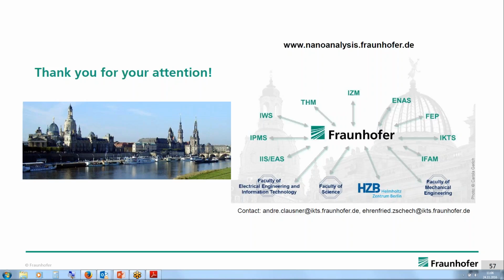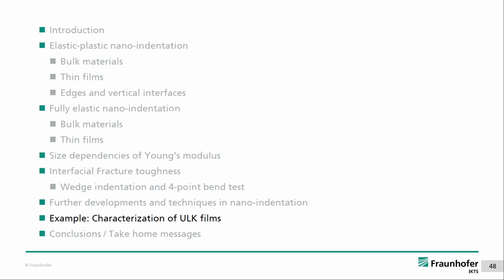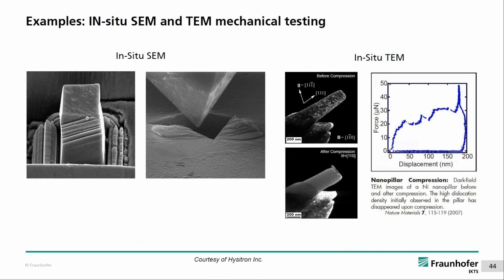The first stage is elastic deformation. If it's a hard material, you can determine the elastic parameters of the nanoparticles from analytical solutions, and if you compress it more and you are in situ, you can see what happens. Either there is plasticity, you see slip lines and so on, as I can show here. This is a pillar, but you can also imagine this is a nanoparticle, and you can see here the slip lines of the plasticity.